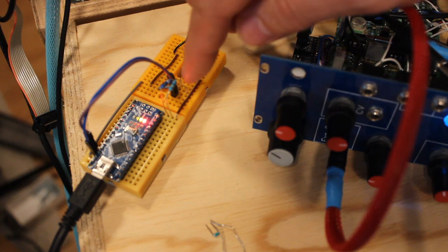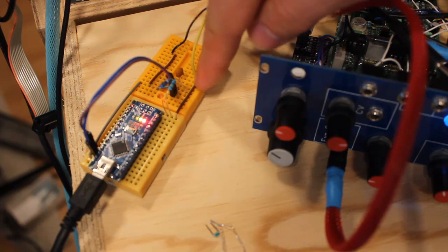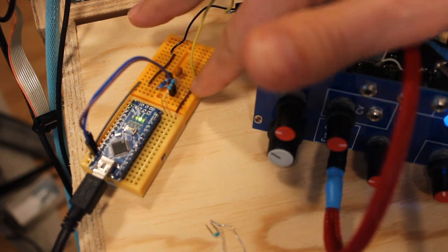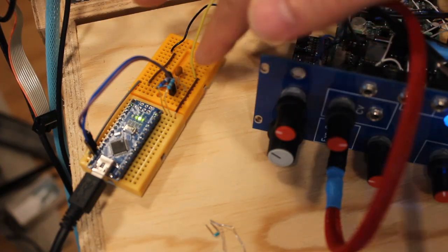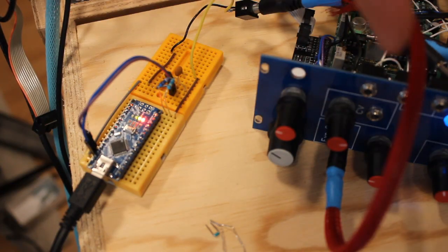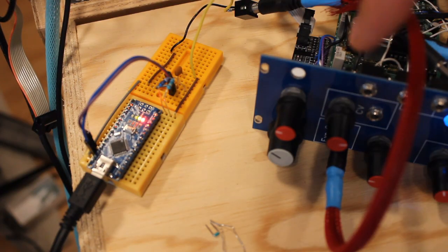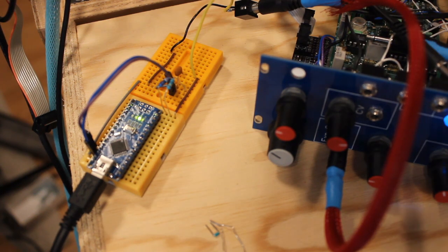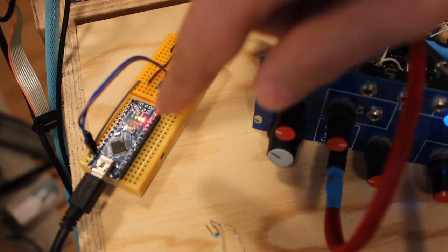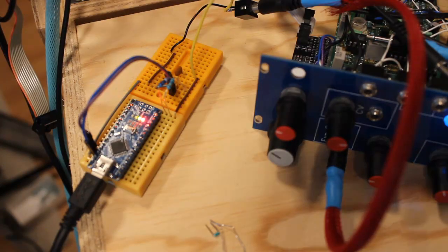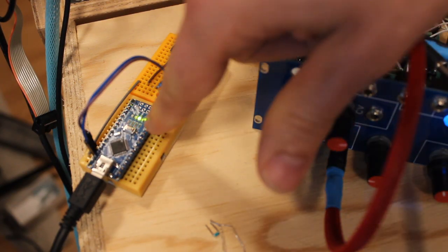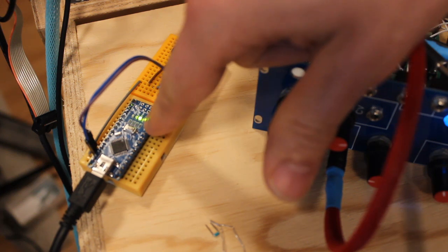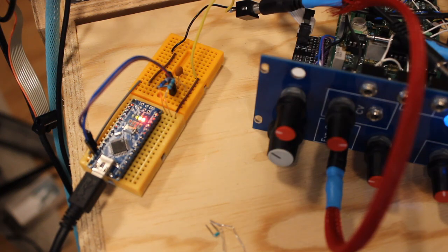So I took the simulation of the simple low pass filter, just one, not the op amp, put it on a breadboard and put it into this really sensitive VCO, exponential CV input. And what you hear is it ramping from 0 to 16,000, and every time the LED turns on or off, it starts a new cycle.